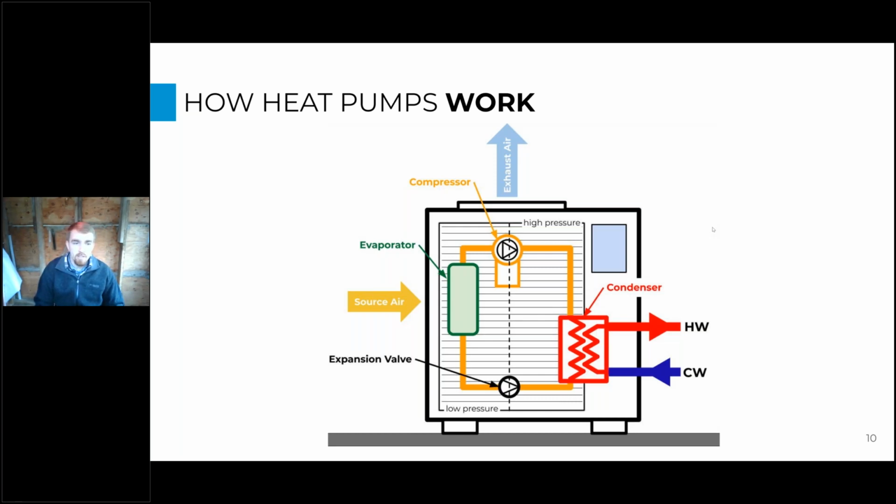And heat pumps have been used for a lot of different applications. We're talking about domestic hot water, but they're also used for space heating and cooling, like your air conditioner in your window or your overall central house system. And they're used in things like refrigerators by pulling the heat out of the fridge and exhausting that into the space around it. So heat pumps are very well proven out, and this is a really reliable cycle. The application to domestic hot water is the only thing that's relatively new to these.